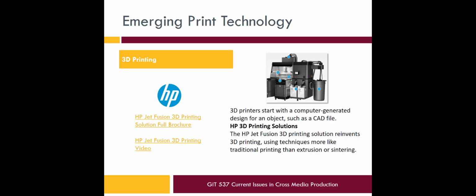Or the other option is laser sintering, where a high-power laser melts or welds or fuses plastic or metal powder into a unified object that becomes solid. Both of those have some limitations as far as speed, because they only add material at one location at a time. Similar to when you're drawing with a pen versus if you're printing with a printer, you can print out a whole row or a whole page at a time.